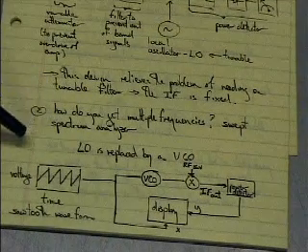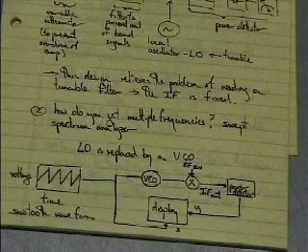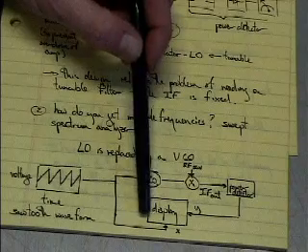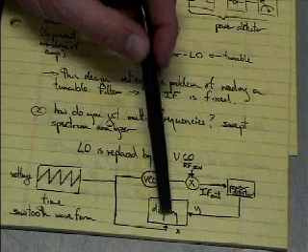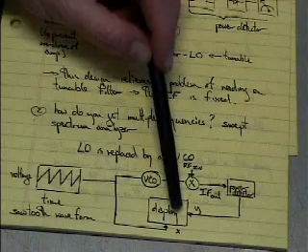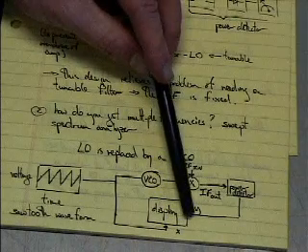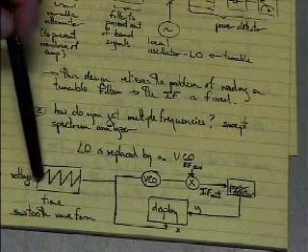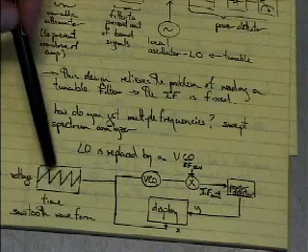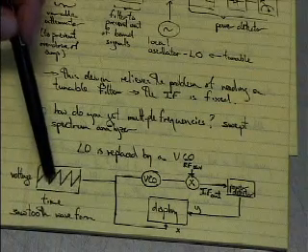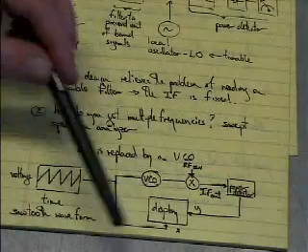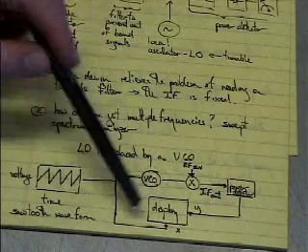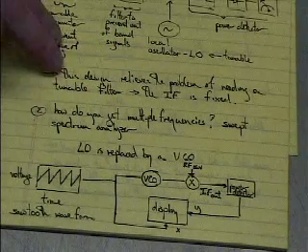Okay, so basically when you're looking at the spectrum analyzer, you're going to see it sweep across. You're going to see the display come across. All right, the power is going to go up and down as the signal components change in power as a function of frequency. You're going to skip back over to this edge, and then it's going to start over again, and that's going to correspond to this ramp going from the lowest left up here to the top, dropping back down again. Okay, when it's back down in here, you're starting another sweep. So this thing's going to be sweeping over and over again, and measuring power of the signal components. All right. So that's what you'll be able to see on the spectrum analyzer.